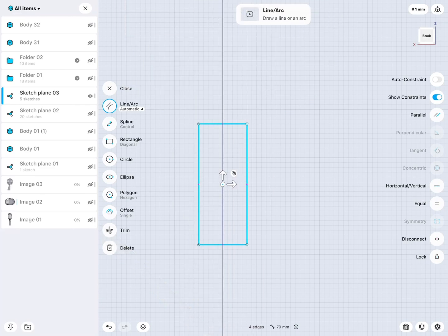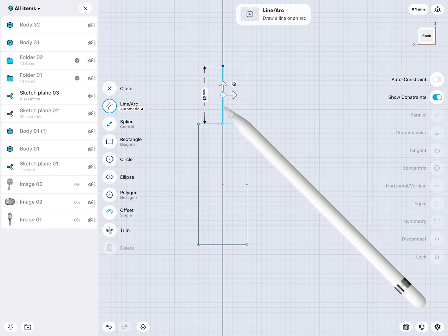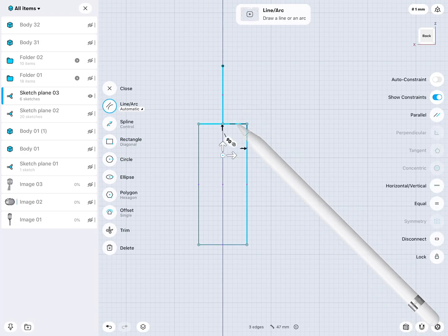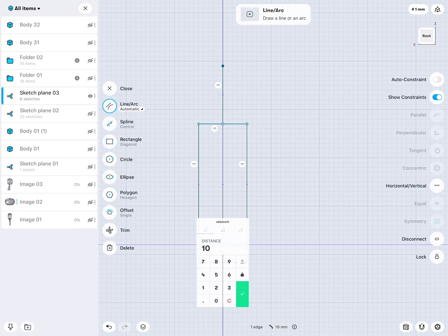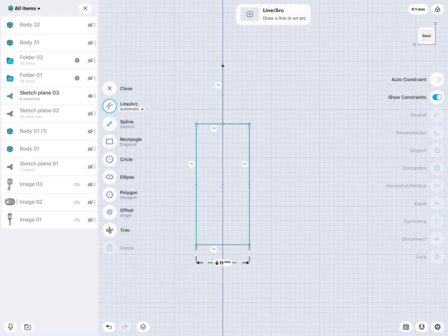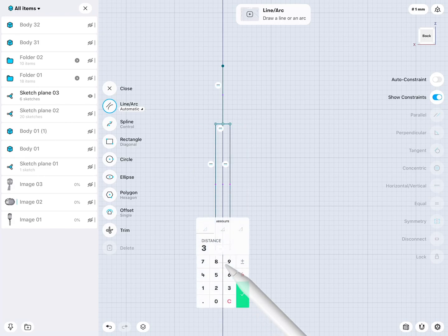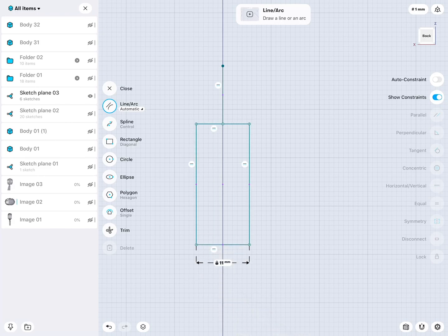I will draw a line to the midpoint, and then this line I put right above it, lock the line, select all these lines, make them vertical, horizontal. Now, this line is perfectly centered on the grid and glued to the midpoint, which means when I select maybe this line here and say you should be 11, you see how symmetrically it expands or grows. Pretty cool.